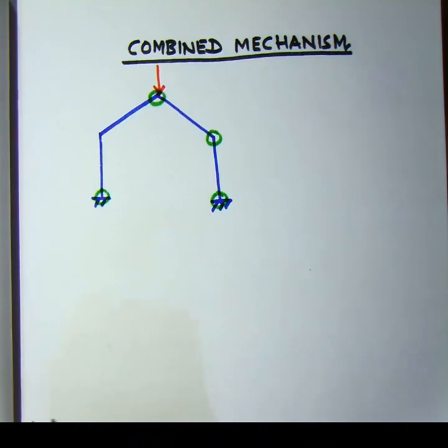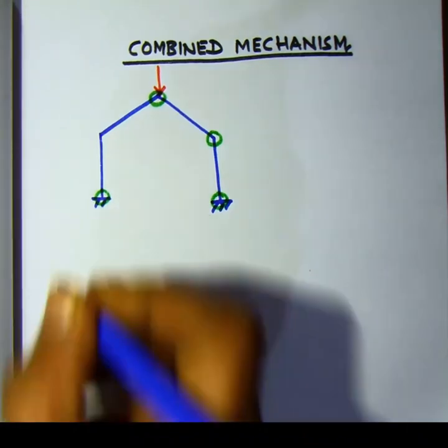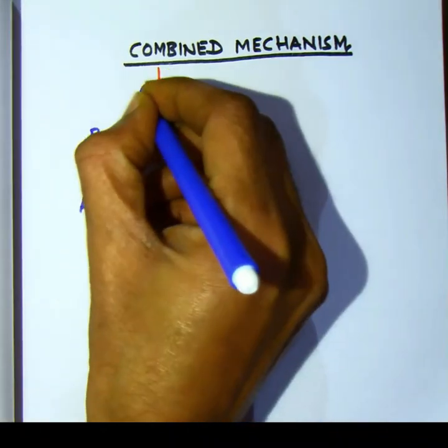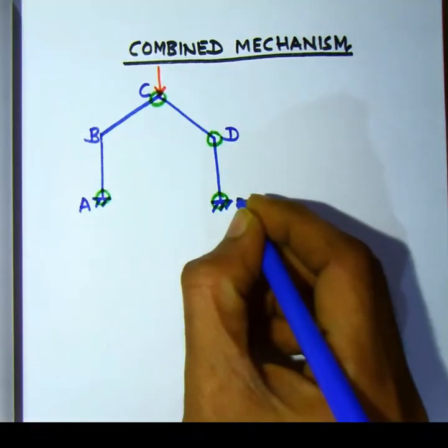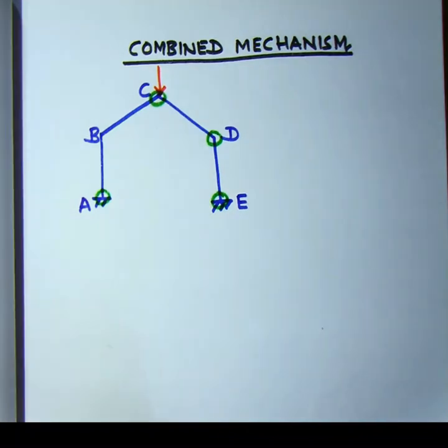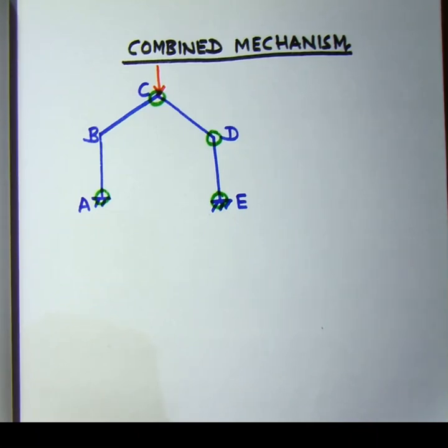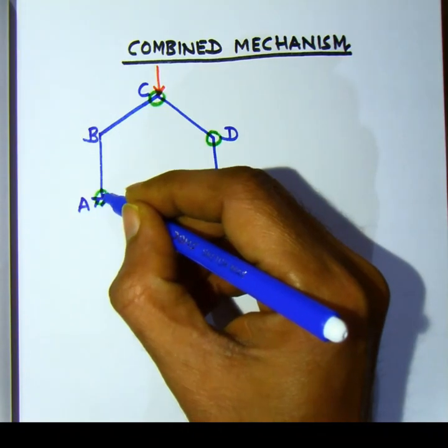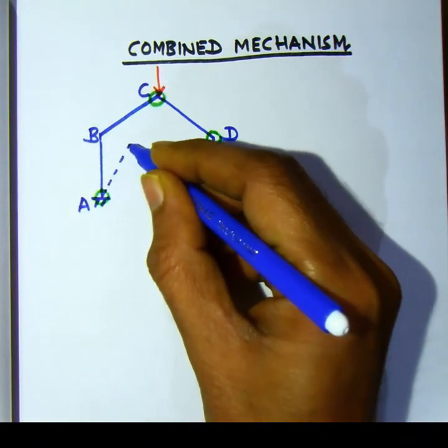As we have learned before, in this mechanism, the left column and the immediate beam, that is segment A, B, C, stays rigid and it undergoes rotation about A. Similarly, D and E, they are also hinged. The only joint which does not undergo hinge formation is B.